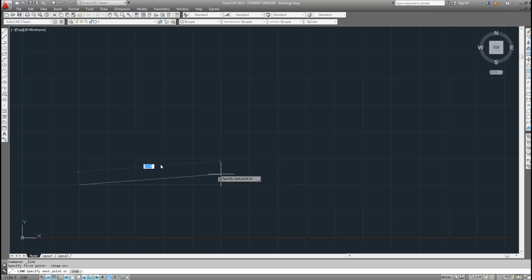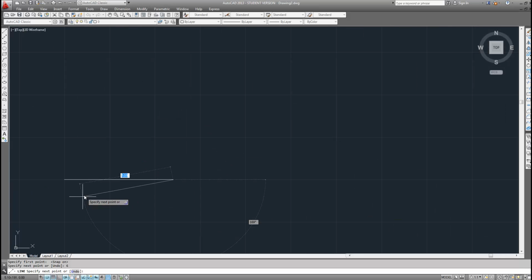Now what's interesting, the last time we always typed in 2 coordinates, a value for the x and a value for the y. But in fact what you can do is just start this line off in the direction you want to go, and do 2 things. Hit 6 and then hit enter. And we went over 6 inches here. And you notice we didn't do 6, 0.